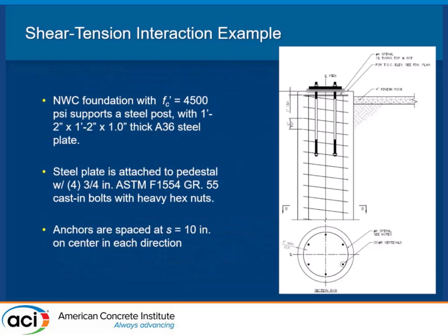As you started to say in the very beginning, this is a good example: we've got a plate on top of a pier here, and I could jump right in and start checking all my modes of failure. But right away I look at it, and I already have some steel here, some longitudinal steel. I know I have supplementary reinforcement. I know that I have these things deep in the ground for whatever reason. If you have a basic design pattern in your firm, remember H effective is going to have to go way up here. Do I even bother